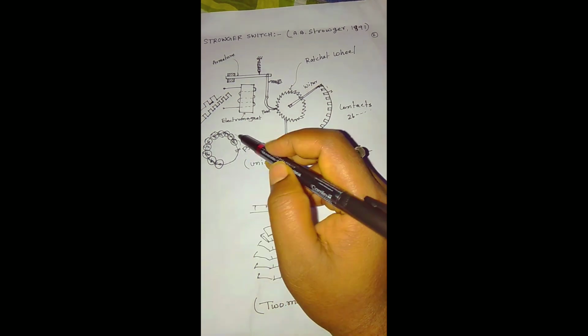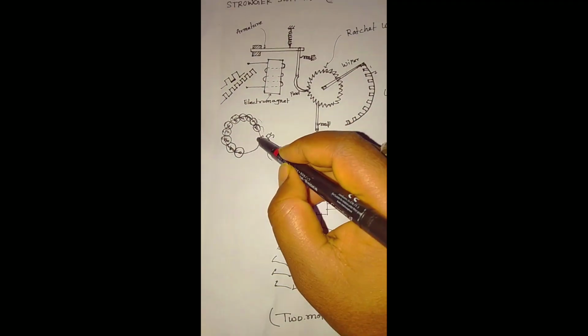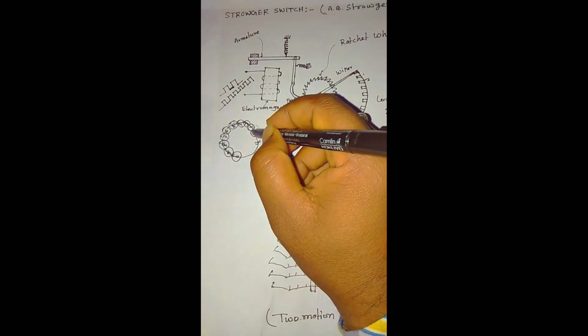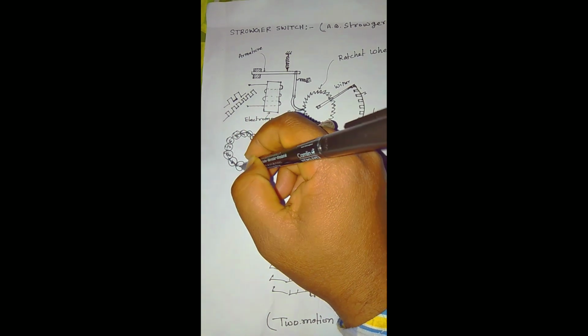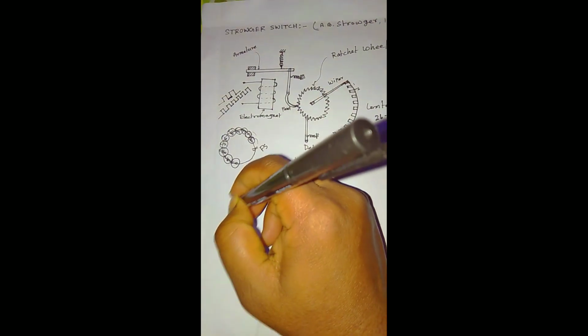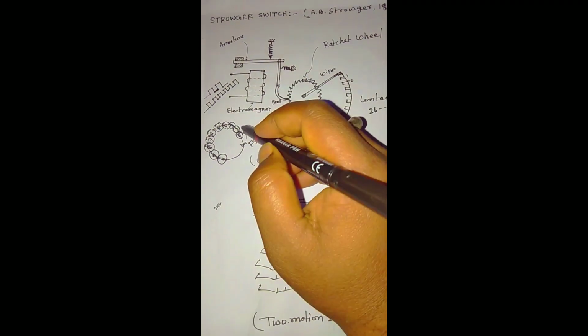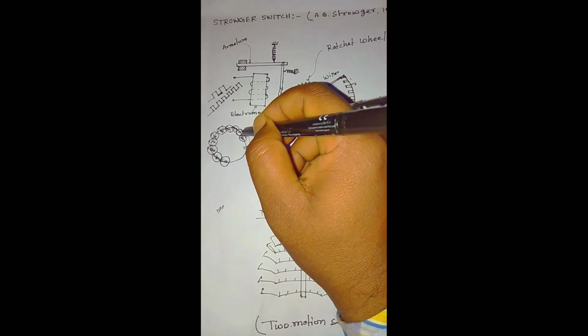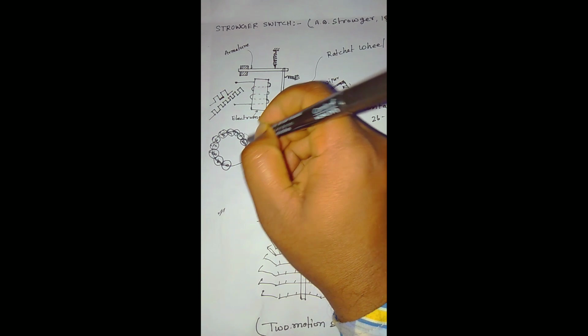Let us consider the example of a rotary dial system. This picture may not be very clear. We have the finger stop, and digits 1, 2, 3, 4, 5, 6, 7, 8, 9 and 0, with 0 over here. Now if we dial 1, it will release one pulse. If we dial 2, it will release two pulses. That is what happens in a pulse dial system.